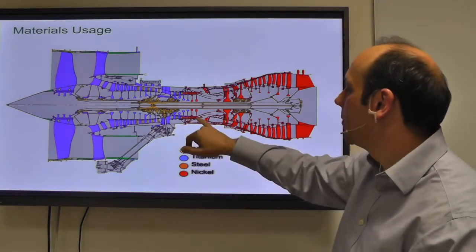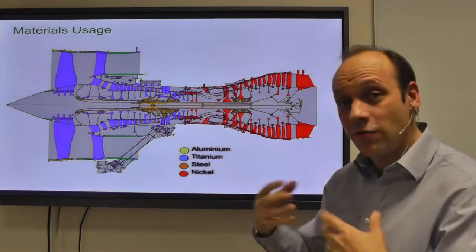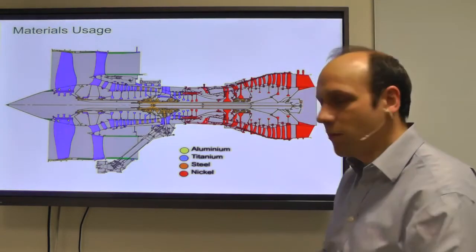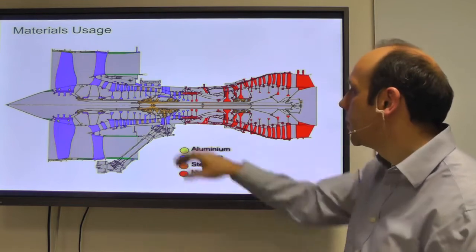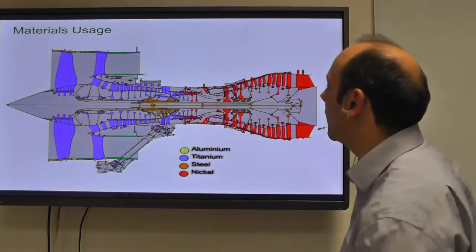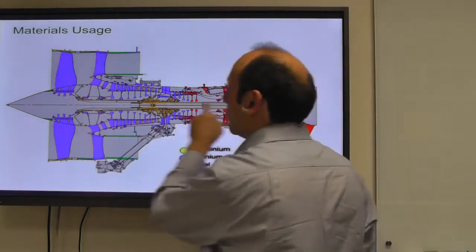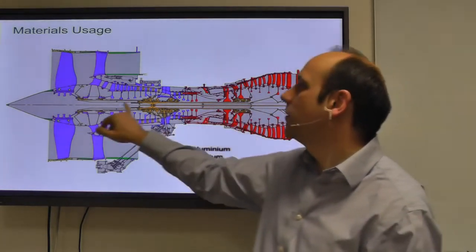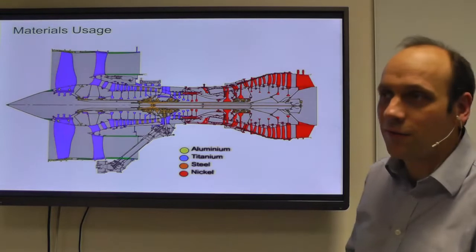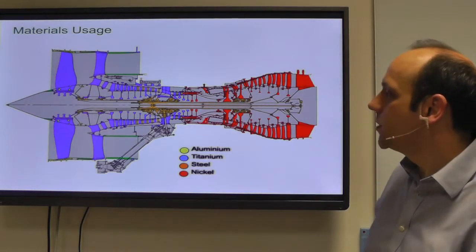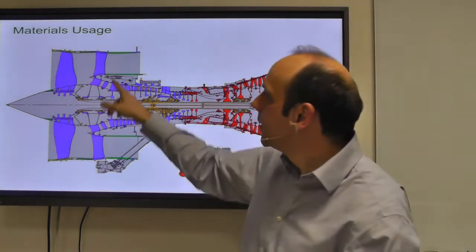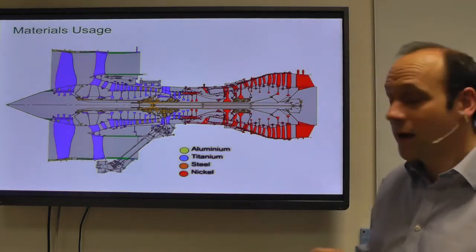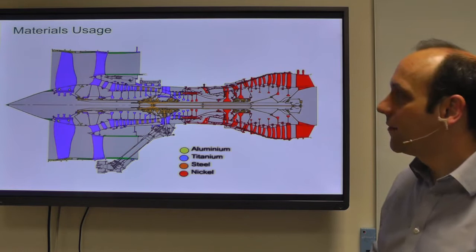And then that's when you start to need the creep resistance of nickel superalloys and the very good high temperature strength given by the remarkable properties of nickel superalloys. And then you're all nickel out the back here. Down through here, your shaft temperatures are probably a mere couple of hundred degrees, and there you're using very high strength VAR steels, things like Jethete, which is making up the shafts. And then this casing here, that could be titanium, that could be a Kevlar composite, various options.